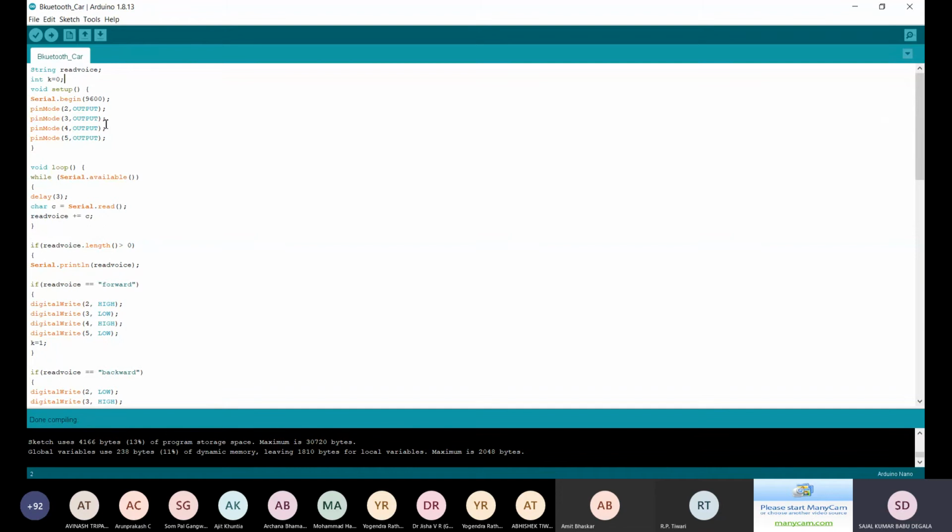Then you have to define whether that variable with the name motor one is going to take integer data, a float value, which means point data like 0.1, 1.1, 2.1, 3.1, or a string, that means a complete word like forward, back, left, right. So if you have any variables that you are writing on your board, you have to write them before the void setup.